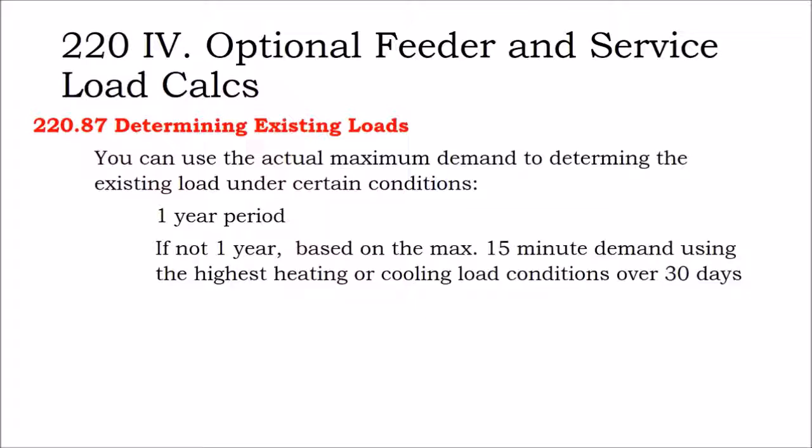So I had a client who wanted to do a 50 kilowatt array on a 40 kilowatt inverter. And he has a 48 kilowatt electric service, 200 amps times 240 volts. A volt times an amp is 48 kilowatts.